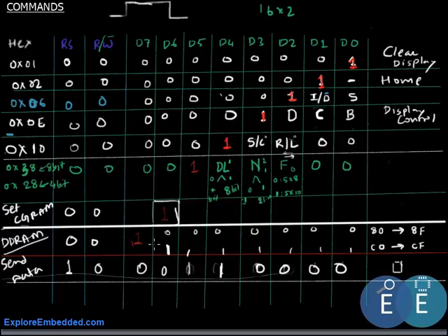Now we will discuss creating custom characters in the advanced video, and a whole lot of other details, since we have 127 addresses but we're using only 80 of these, or eventually only 16 for the first line and 16 for the next line. We will discuss the internal RAM structure and its relation with the CG RAM and how it generates the characters from the given ASCII value. So we will discuss all that in the detailed video.